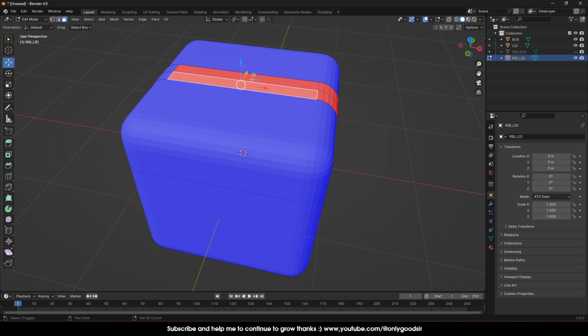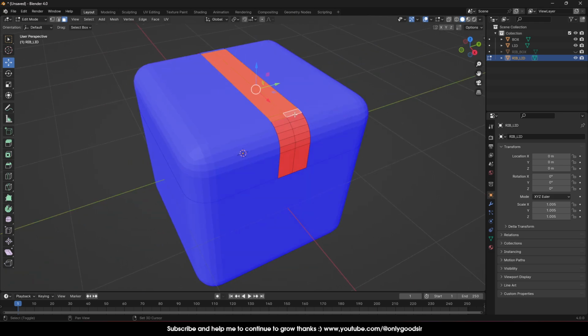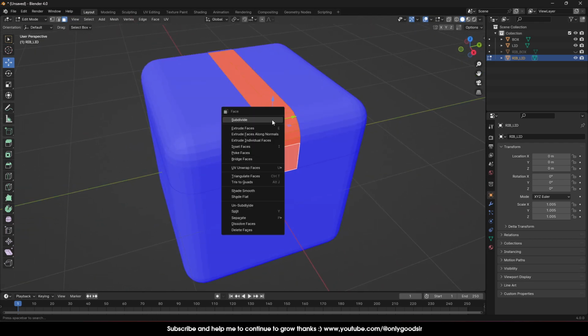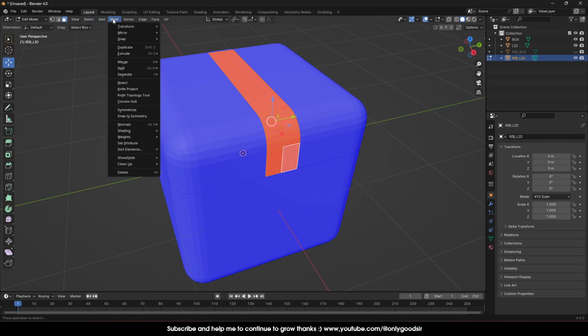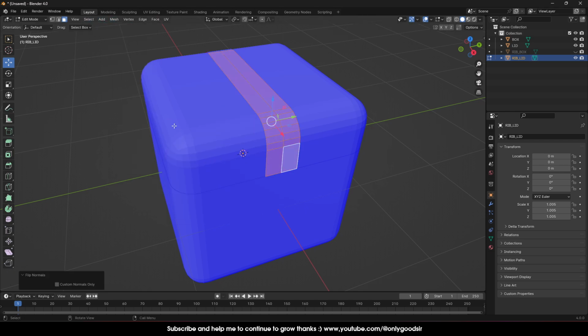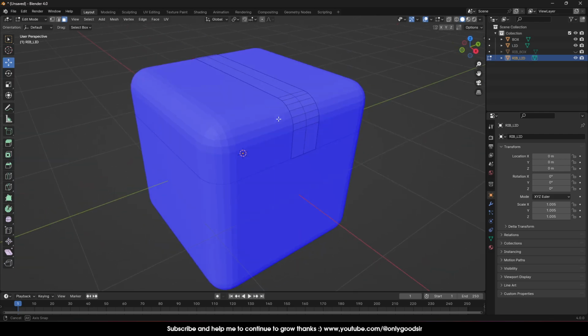So I only noticed this on 4, but I always double check on 4. In the older ones, I never noticed this, but on 4 I've noticed this happen a bit. But I'm gonna right click, sorry, don't go to mesh, normalize, and say flip. There we go. That solves our problem.